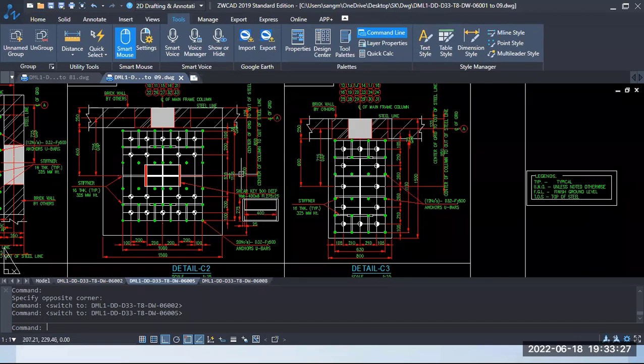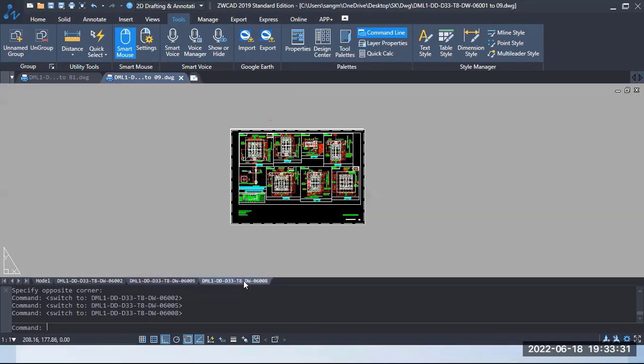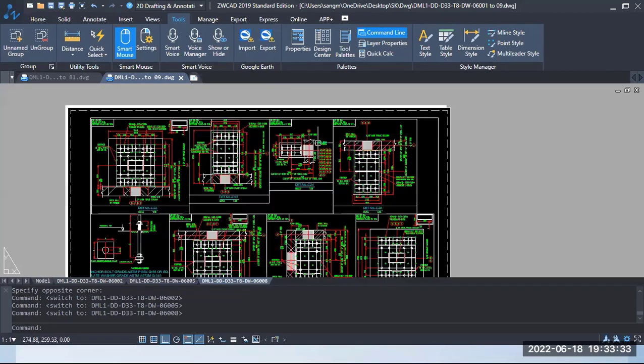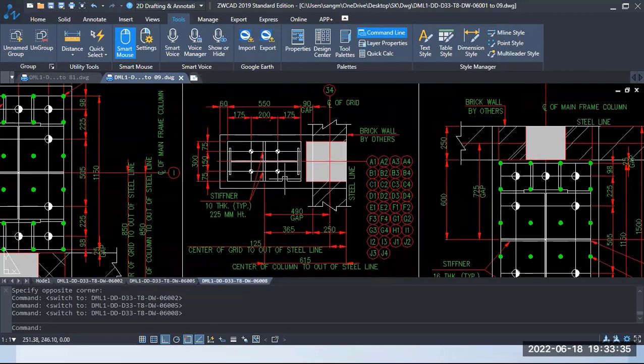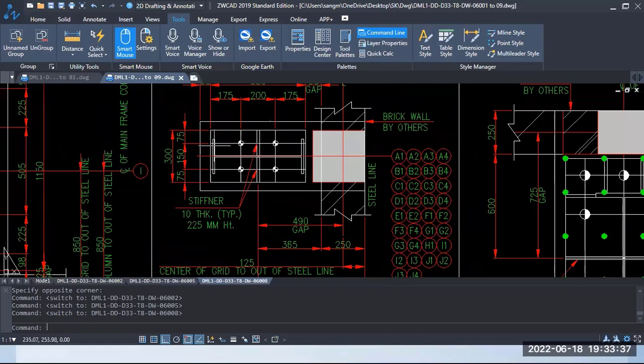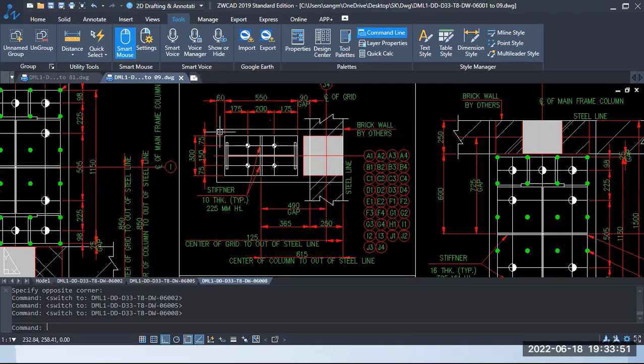This is an example of the fixed base, and I can show you another example, the pin base. Here is the pin base detail. We have all the bolt heads inside this flange, so as to avoid generating any lever arm between the bolts. Automatically the lever arm will be reduced in this bolt, so it will behave like a pin base. So this is what we have provided for the end wall columns.